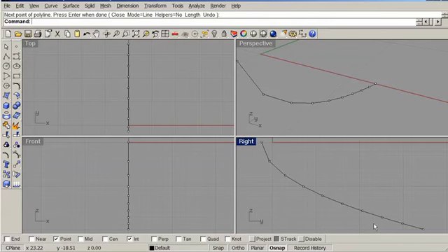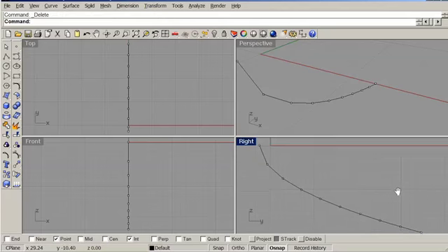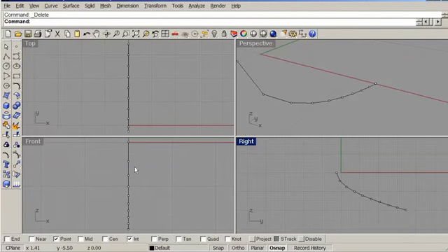Okay, so now I've got my parabola. Now the other thing I need to do is to define the end of my parabola, the output face if you will, and I also want to facet that. So to do that, I need to draw a circular extent to my parabola. First, I want to zoom out a little bit so I can position it better. And since this is drawn in the ZY plane, I'm going to put the circle over here in my ZX plane.